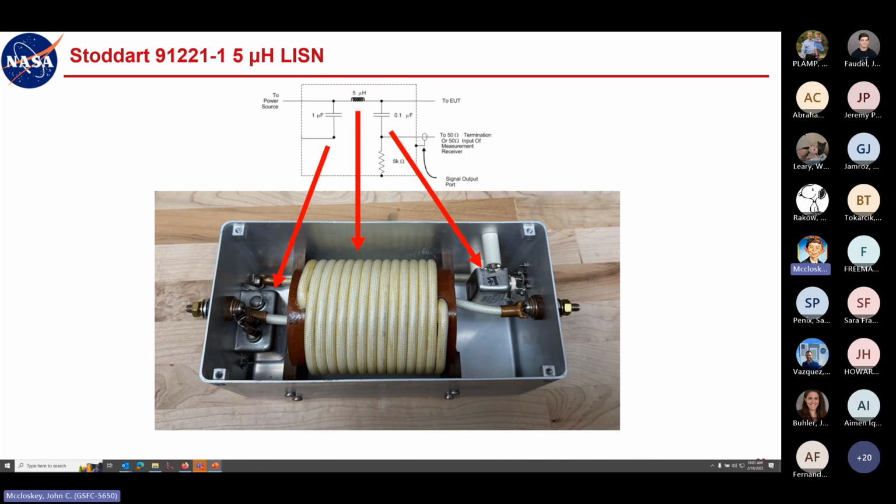So you don't get 5 microhenries of stray or leakage inductance. If you're talking stray or leakage inductance, you're talking tens of nanohenries, maybe 100 nanohenries. To get 5 microhenries, you have to mean it. And even that's just way overkill for the kind of inductance you're likely to see on a power bus. When you have a dedicated return wire twisted with your send wire, you're going to have, again, tens to maybe 100 nanohenries per meter. So, okay, I misspoke slightly.